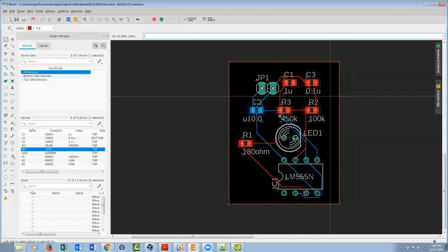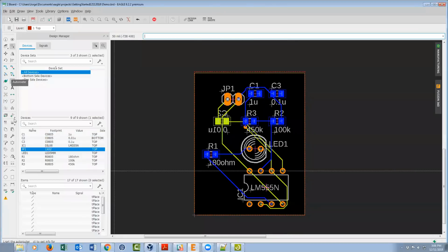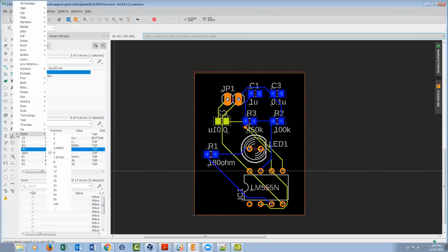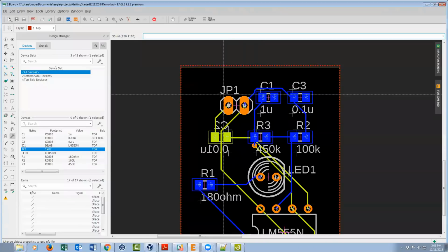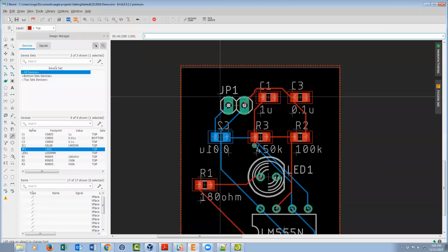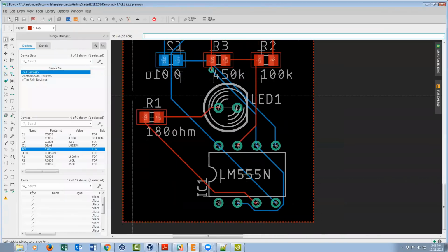So just to show how you can set everything to be vector font, you just basically group everything. You go over here to the change command, which is the wrench. You select font, vector, and then to apply the action to the group, hold down Control and right click. And you'll see that everything changes. Okay? And in that case, it really is set to vector.